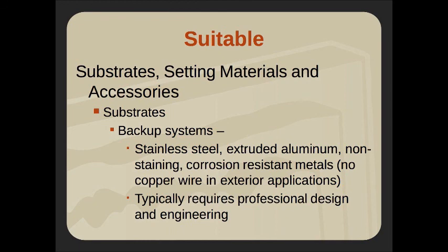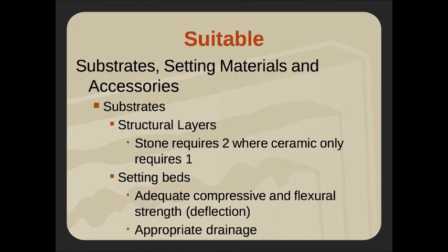This is where your engineering, your qualified installers come in, where they can design a system that's appropriate for what you're trying to achieve and get the engineering calculations on the back end to justify it. Structural layers, you know, stone we might need 2, or ceramic only requires 1. Setting beds, are we getting our adequate compressive and structural strength? Are we taking the deflection into mind?